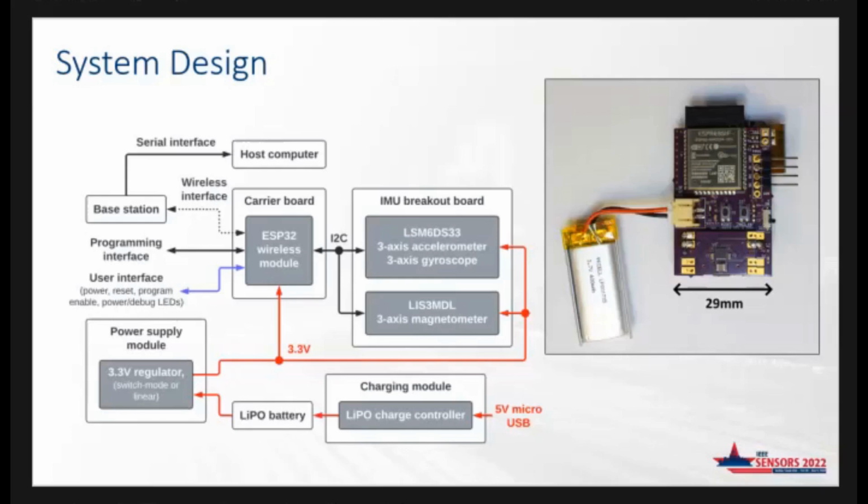So in essence, the controller is responding to queries from the base station, and then samples the IMU sensors, gets the data, and then transfers it back as a 44-byte packet. And then the host does this for each of the 8 sensors in the network, passes that to the host computer, and then the processing is done on that end.